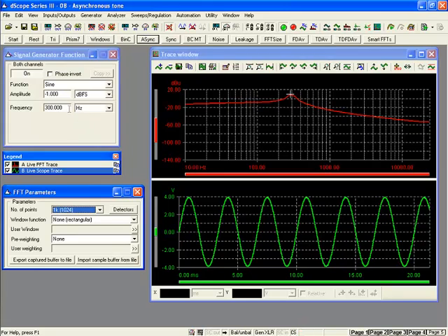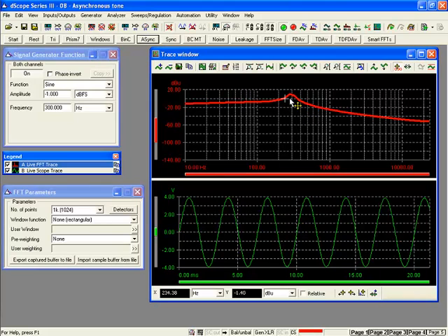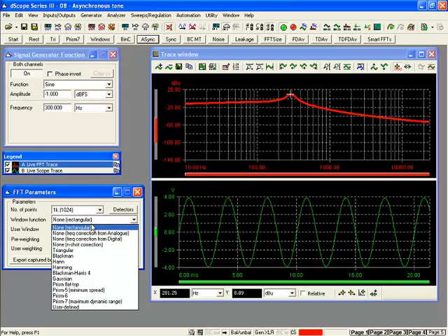We can see clearly that when we take the arbitrary frequency of, in this case, 300 Hertz, the capture starts on a zero crossing. That's how I've defined my trigger, more on that later. But it doesn't finish on a zero crossing. And this effectively shows us this discontinuity between the start and the end of the buffer, which shows up as this rather messy frequency response when we use a rectangular window.